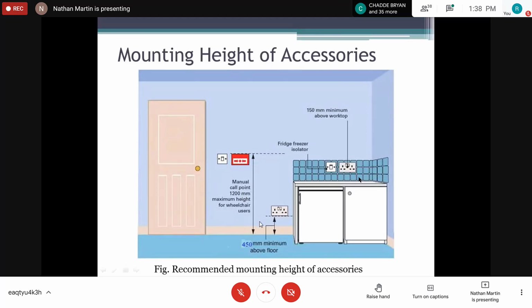However, when we talk about height from the floor, we're talking about from the finished floor, right? So if you are doing a new installation, guys, you need to make allowance for your tiles. But what if they never put in the flooring before and you need to position your boxes? On the diagram they will indicate the height from the finished floor to the ceiling.